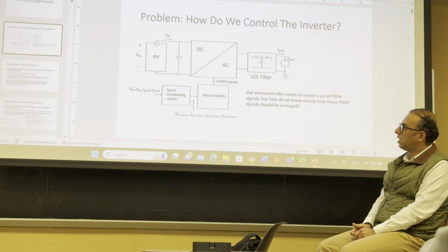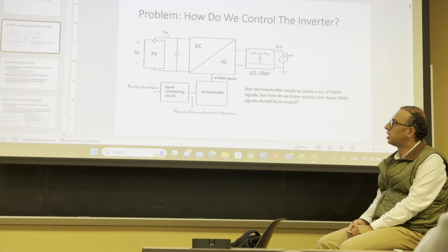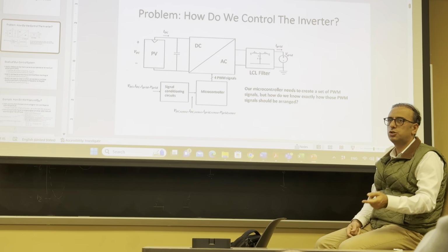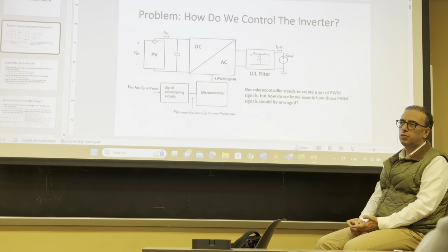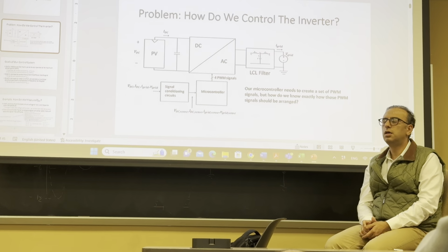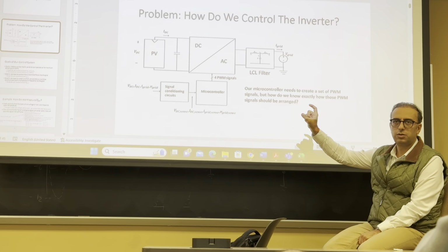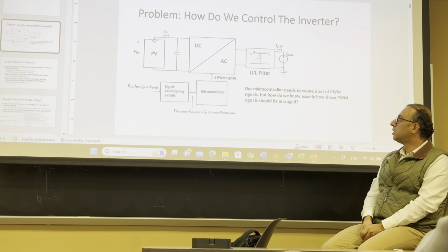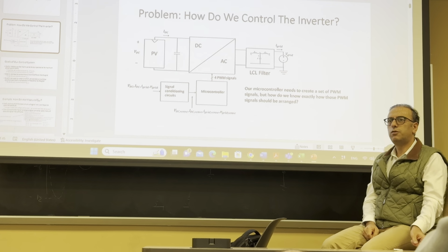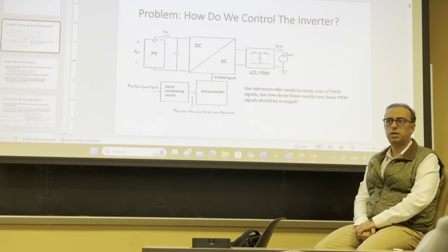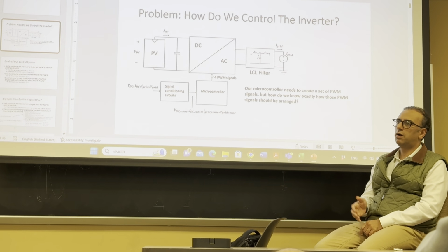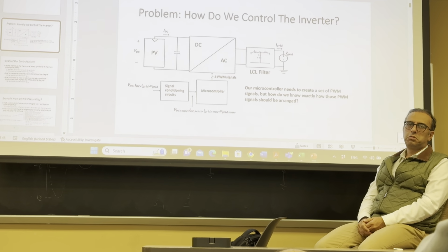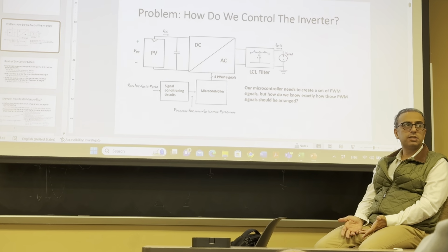So, what do we need? In general, the photovoltaic system, as I said, is a voltage-controlled current source. So one way to track the sun is to control the DC link voltage. So the first thing that you need measurement for is the DC link voltage. Then we talked about single versus double loop systems, and we saw that at least in our systems, you have at least one inductor and one capacitor, which exhibits a second order system.